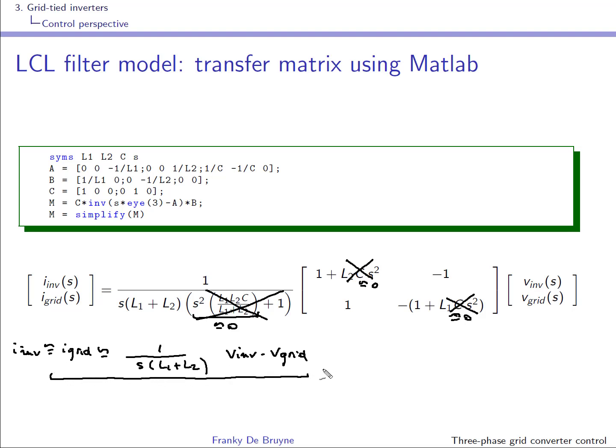So this is kind of saying that if you forget the high frequency dynamics, because we're not pushing our controller too far to have a high bandwidth, we can use a simpler model for control design, and this simpler model is simply this model over here. We forget about the capacitor, and if we forget about the capacitor, you end up with an inductance which is L1 plus L2.